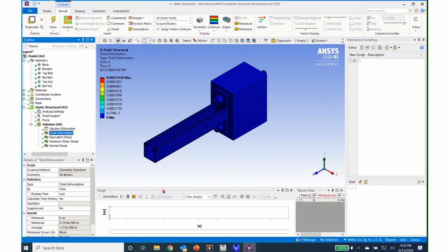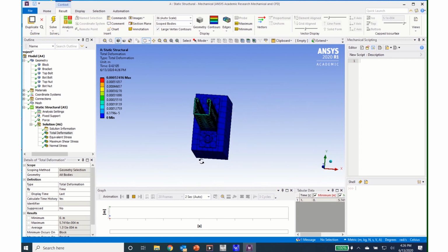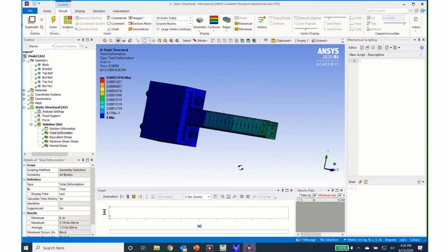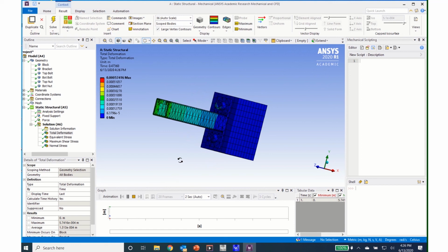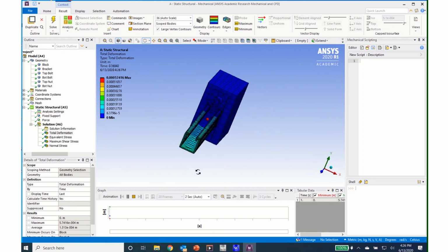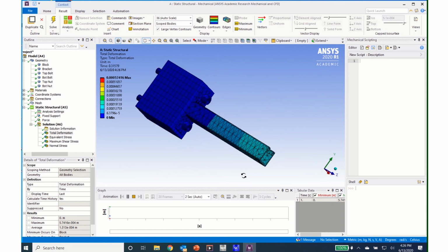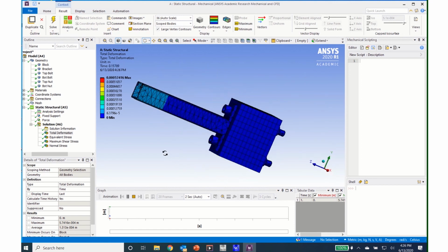And this is often helpful to make sure that the loads that you are applying give you the correct deflections, and that the load path can be validated. So this looks like what it should with the loads that we gave it. This beam is very stiff in the up and down direction, so we have a lot more motion in the X direction than we do in the Y direction, based on the loads that we gave it.